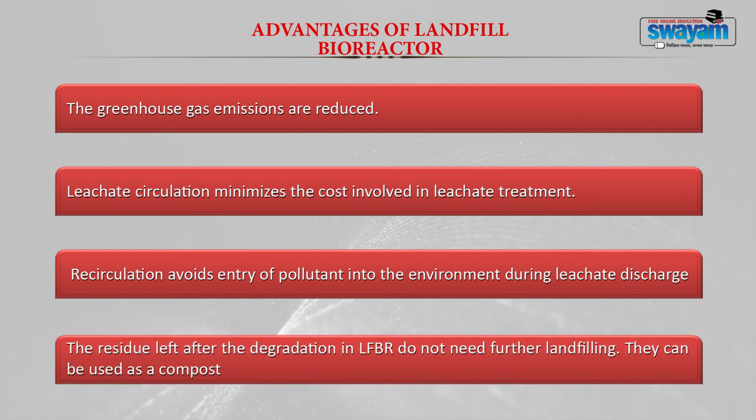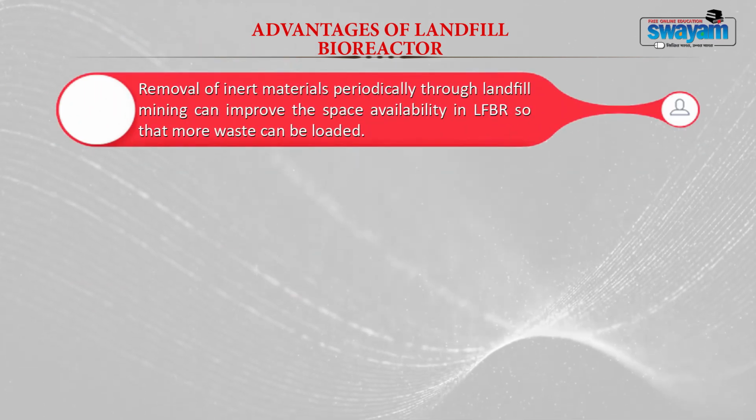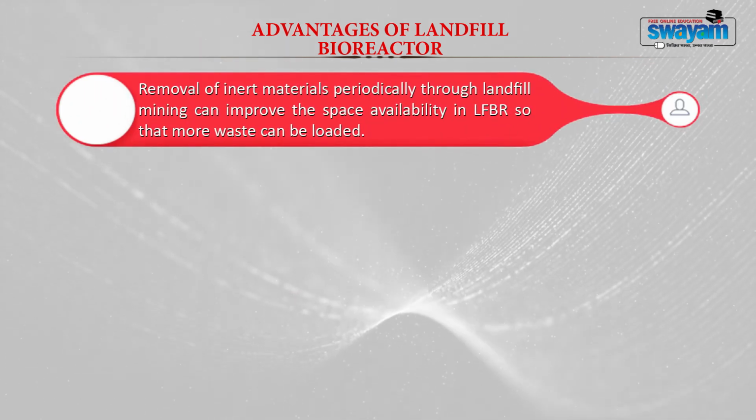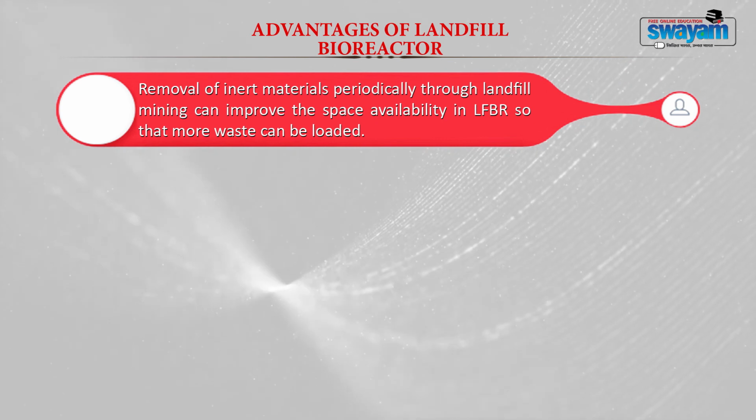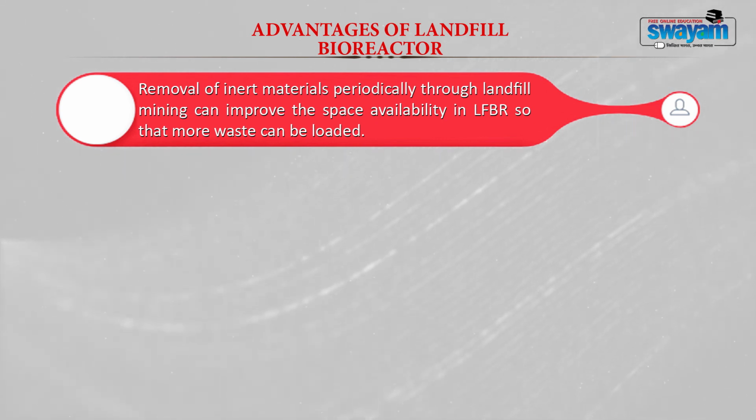Now, the residue left after degradation in landfill bioreactor does not need any further landfilling because the degradation would have occurred completely. Now, in a landfill bioreactor, inert materials can be periodically removed through landfill mining, and this can again improve the space availability in your landfill bioreactor so that more waste can be loaded.